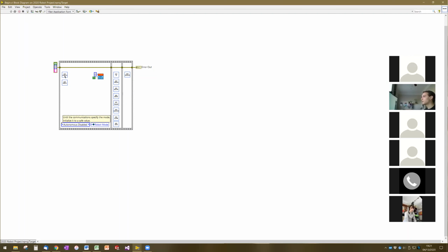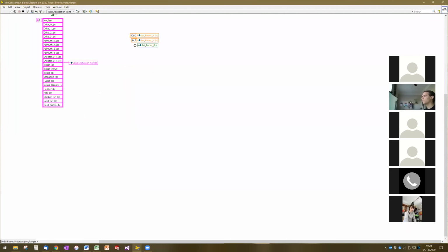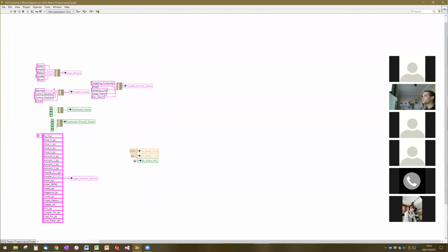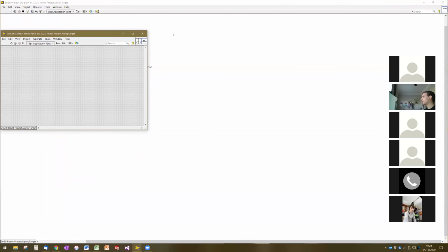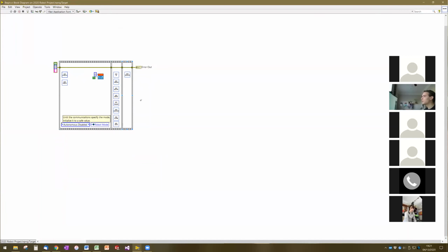Some of the constants have to be initialized first, for instance, what drivers are available, what states exist, and what position the robot's starting at. Those all have to be initialized before we get to any of the motor initializations. And then because of the way the IMU is hooked into the control system, the motors have to be initialized before we initialize the sensors. And so we have a little bit more structure for initialization than the first default.